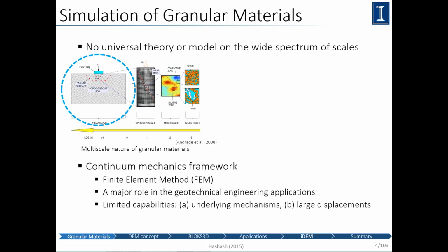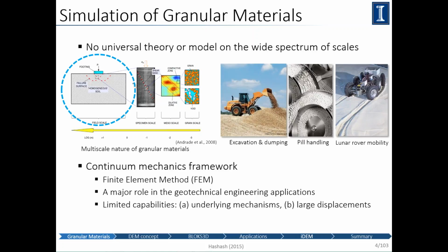That is when we develop a shear plane in our granular material. That doesn't work as well for us. Also, how do we deal with a continuum framework when we are working with excavation and dumping, or something like pill handling or lunar rover mobility? There the material sometimes behaves as a fluid and sometimes it behaves as a solid, and you cannot represent it readily with a continuum mechanics